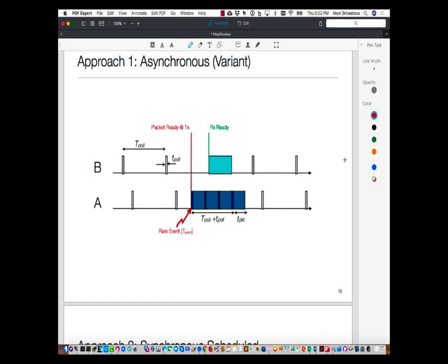If it gets in the middle of the preamble, yeah, then it would see junk basically. And so it will wait. Basically, what the receiver does is it will say, there is energy on the channel. Let me take my correlator and keep matching, and the match will only happen in the next preamble. Okay. And then there is yet another variant where in between packets we leave a little bit of a time so that the receiver can say, hey, I received the packet. And all of these things are playing around with the latency energy trade-offs, basically. Okay, so that's basically what's happening out here.